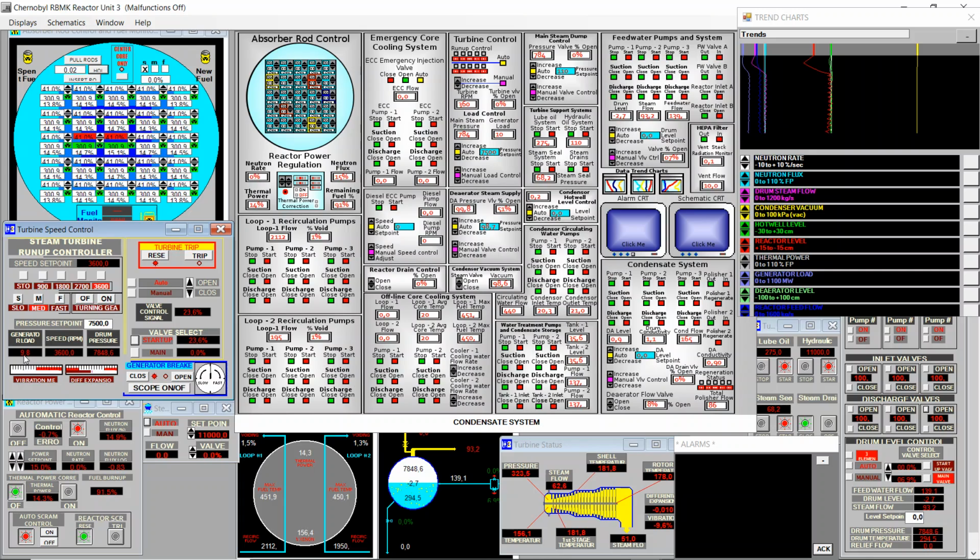Okay, so it stabilized, it went down to 6, and now it's going back up to 20 or something. We'll wait a bit for this to stabilize. We also see the spike, or the dip, that it made in the reactor level. I guess this is because the opening and closing of the two valves is not in perfect synchrony. So one starts closing before the second starts opening or something like that.